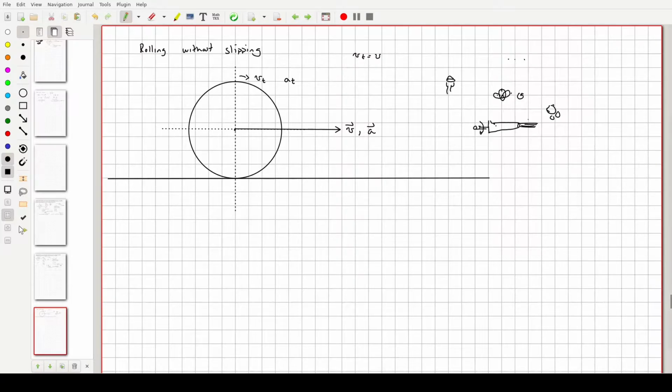The drive shaft spins like this and is attached to the rear axle. And this right here comes out. That's what you see there. That's your rear axles right here. And there's gear work in here so that as this rotates, it takes this rotation right here and makes it like this. So all this is rotation. So your engine works off of basically rotational motion. And that rotation is the reason why your wheel rotates. So as your wheel rotates, you put it on the ground, and you take that rotational motion and put it into translational motion.